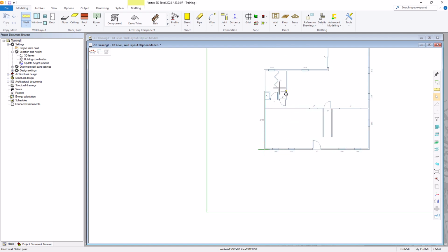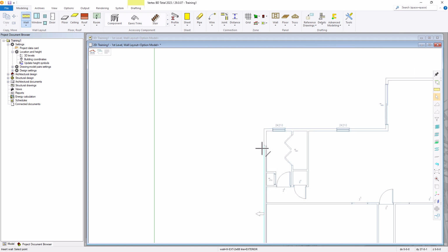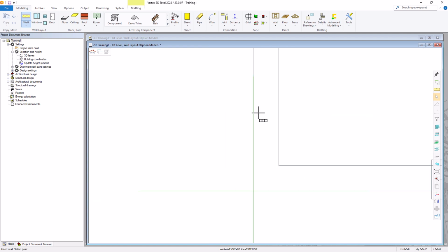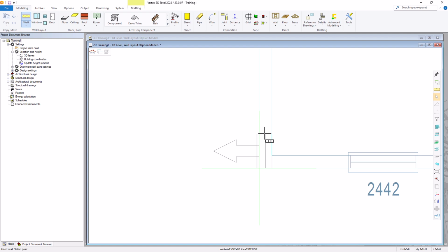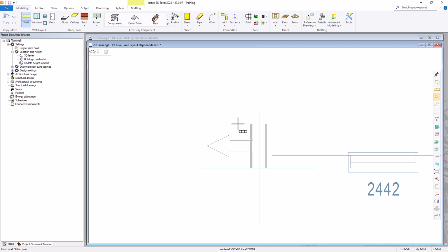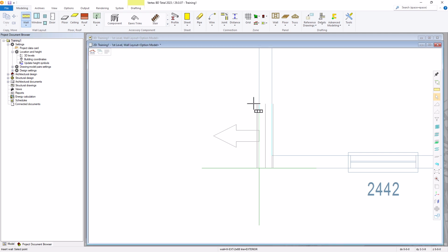And now we can go up and select our exterior corner. Now, if your wall is not correctly lined up, you can right click and adjust the wall placement. So in that case, we see the center line of the wall is lined up with the exterior of the CAD drawing, which is obviously incorrect. So just use your placement lines until it looks correct.